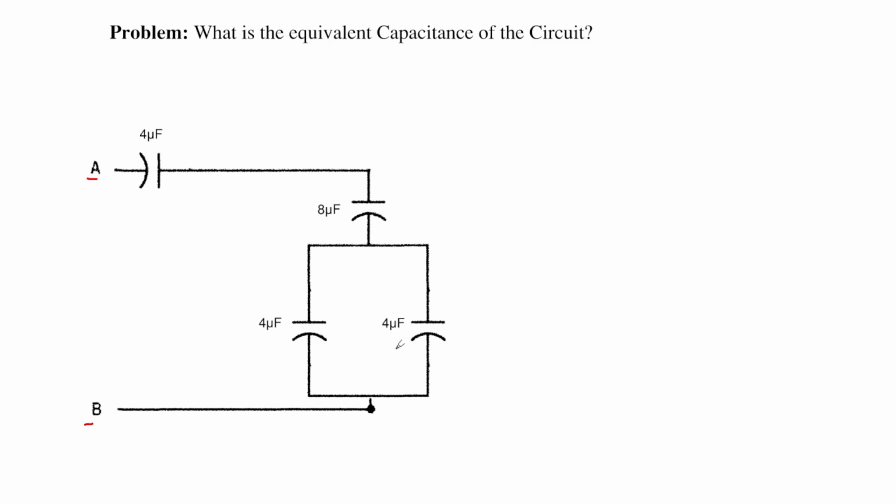Now, in creating equivalent elements of capacitors, we need to realize that it is opposite to how we approach resistors. Therefore, when two capacitors are in parallel, we simply add up their values, and for series sets of capacitors, we will need to utilize reciprocal laws.